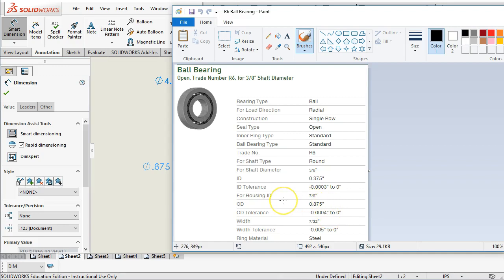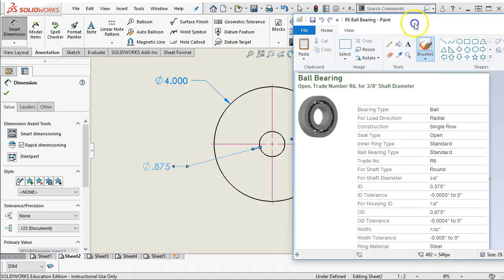If I cut that right at 875, it slips in, and the hub of the pulley now spins on the outer race of the bearing, and the bearing does me absolutely no good. If I don't have that physical interference, that physical contact between the pulley and the outer race, what do I need it for?